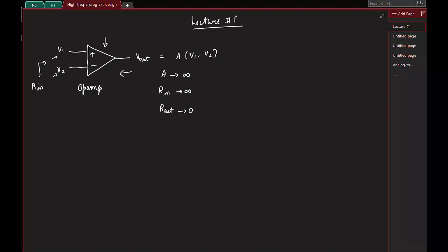My question is, you seem to have an infinite gain times some input voltage, right? So if I directly give some voltage here, the gain is infinity. What will happen to the output? Ideally it will be infinite, but in practice it gets saturated to the supplies and grounds, right? So what's the point of this infinite gain?